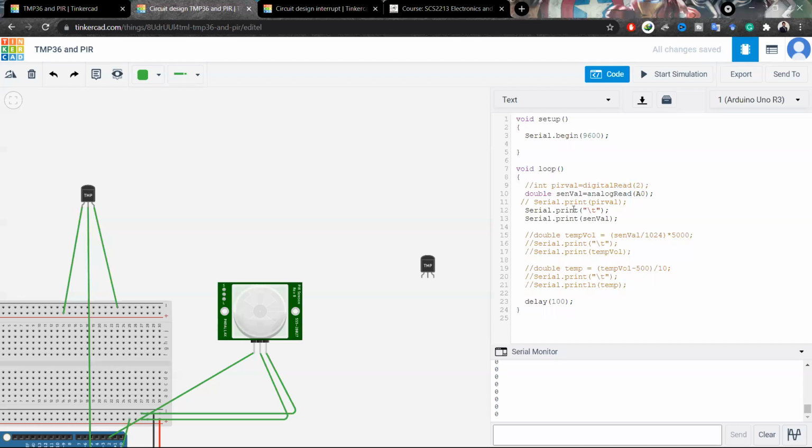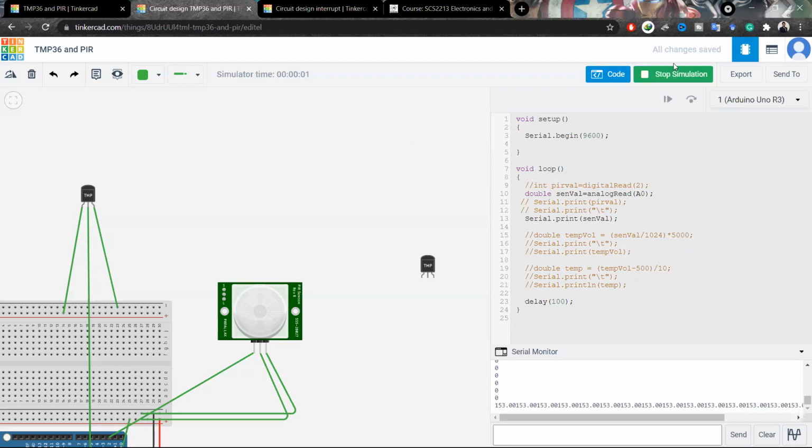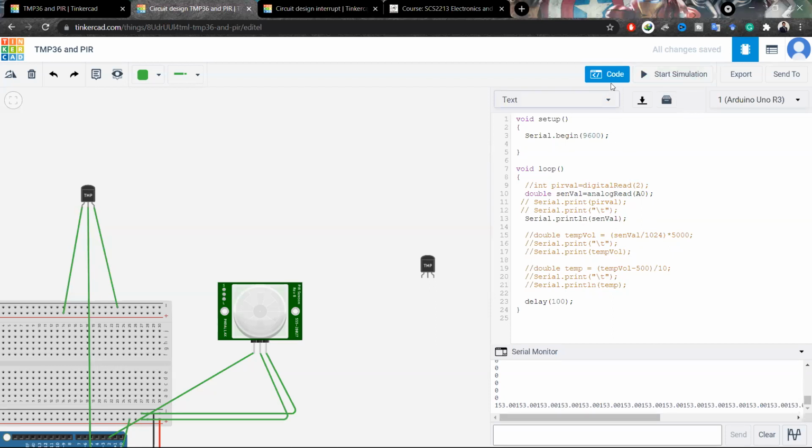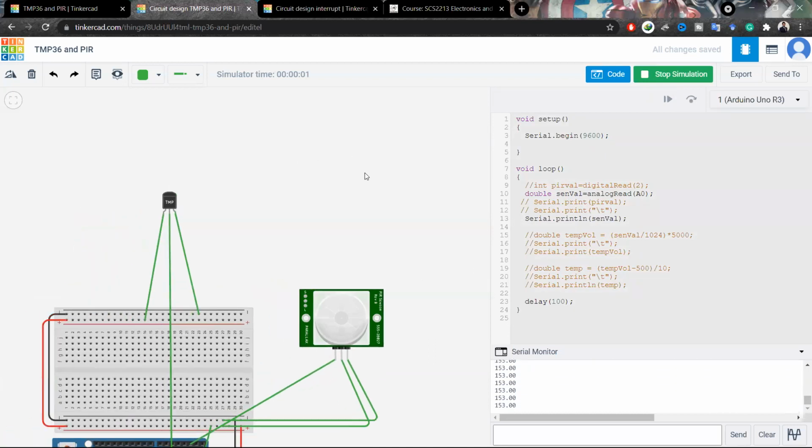Then I'm going to print that value. So I start Serial.begin at setup, specify the baud rate as this, and give some delay. Now the things are okay, it should start to work. Okay, I should put println in here. Okay, now it's fine.